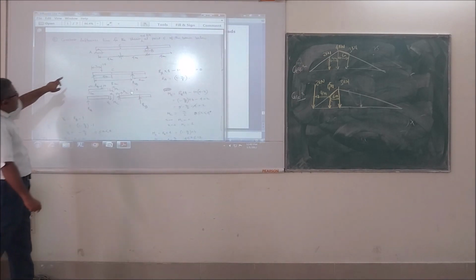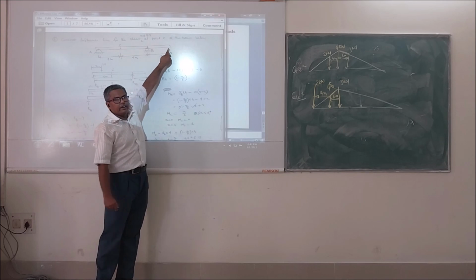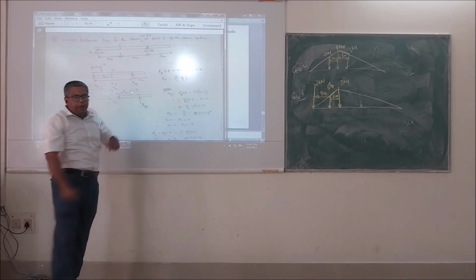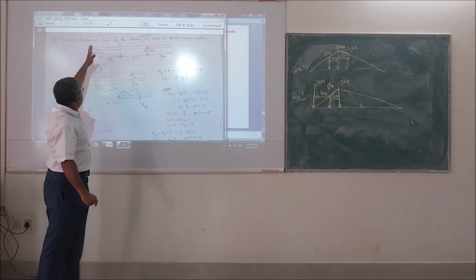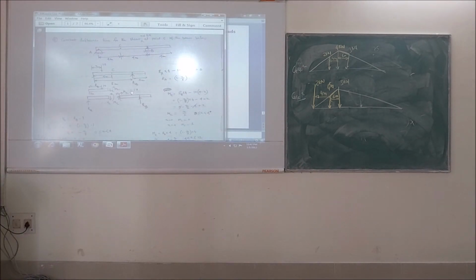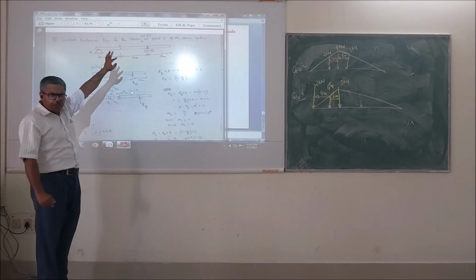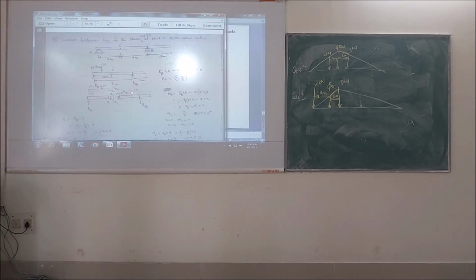Okay. So you see, what is happening to this kind of beam? What is this beam? This is a simple supported beam and it has the overhang, right? So this much portion is overhang. So it is a 4 meter, 4 meter, 4 meter beam. So 12 meter is the total length of the beam. Simple supported portion is 8 meter and there is an overhang of 4 meter. Okay? See, overhang can be on this side, overhang can be on this side also. Okay? So both way overhang beam is also possible, single way overhang beam is possible. Now, if you want to construct the influence line for bending moment or influence line for shear force at point C over here, and C is the middle position of the simple supported portion of the beam.